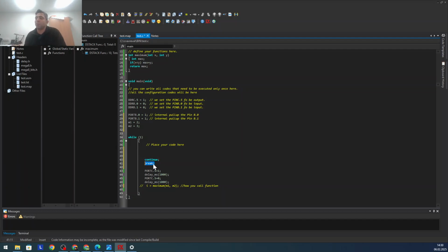So we don't write break here, otherwise the program will come out of this while loop, and after this while loop there is nothing, and the program will finish, and basically it will shut down. We have to reset the program, and every time you reset it will see the break and get out, so the program will not work long. So let's delete the break.